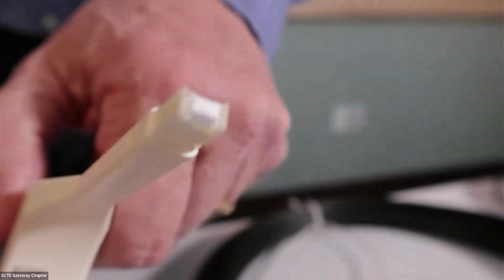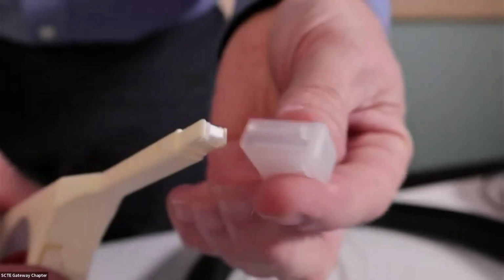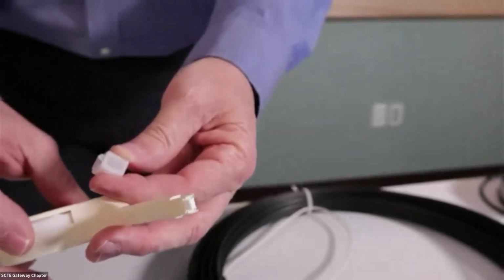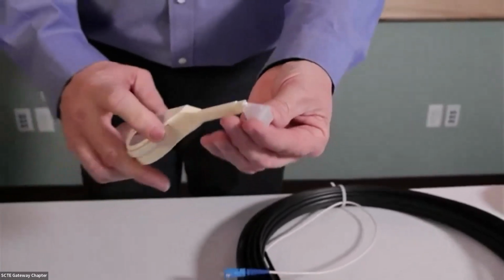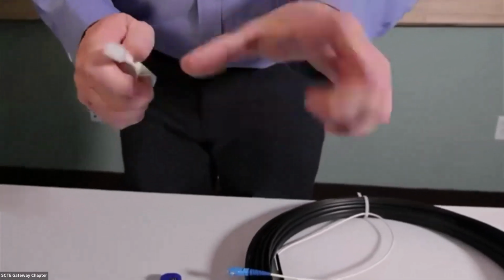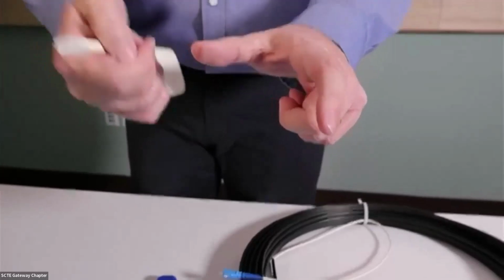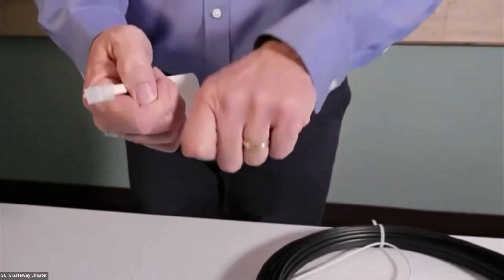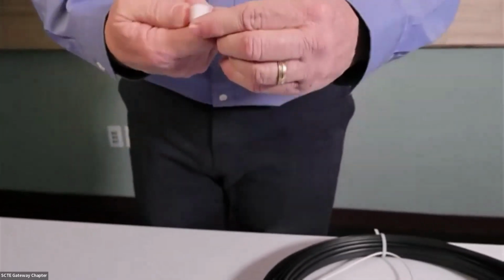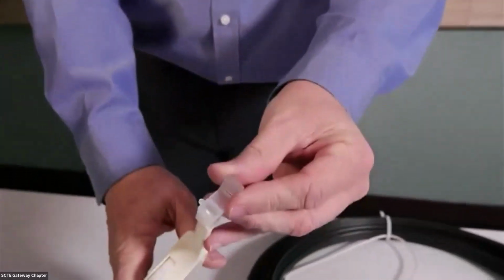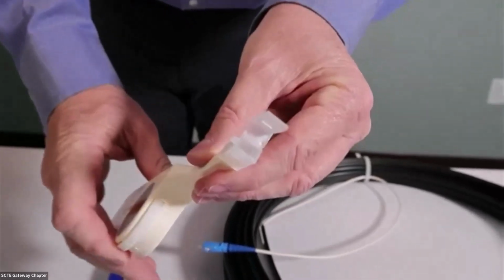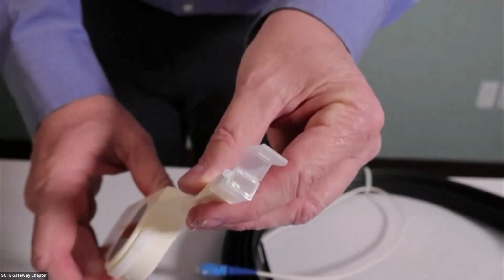This one here is a newer version of the clay top version where you actually drag a thumb wheel and every time it stops, it cleans. You might have seen those before. They're usually a green or a gray box that has a thumb wheel, exposes tape, and you rotate and pull fibers down. You don't see those as much as you used to. But this style here, you would put an MPO connector on the inside and then rotate the wheel to clean the fiber.